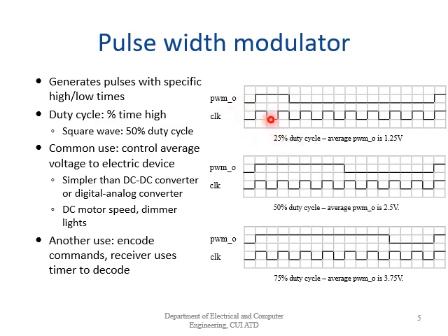In the first graph, you can see that if we have a maximum voltage of 5 and our duty cycle is 25, it means that we are going to turn on the signal for 25% of the time, it is going to be high, and 75% of the time it is going to be low. So if we multiply 5 with 0.25, we get 1.25. So the average voltage of the PWM is going to be 1.25.